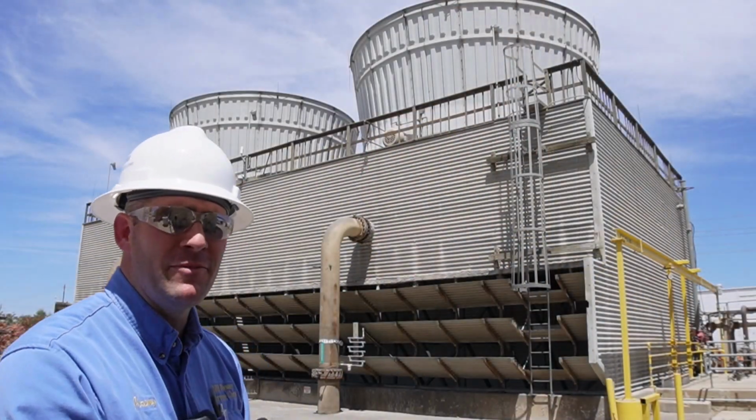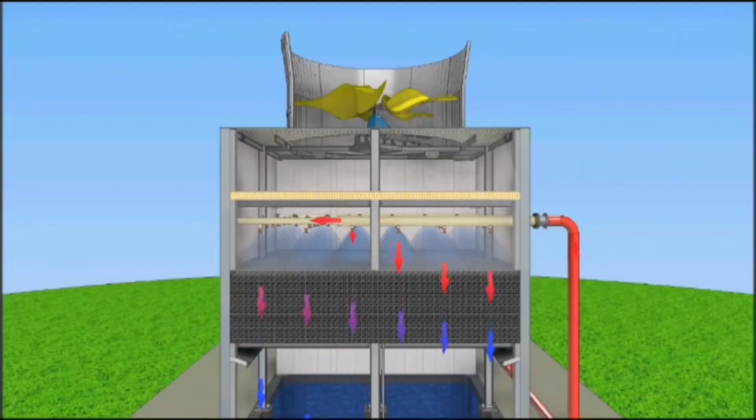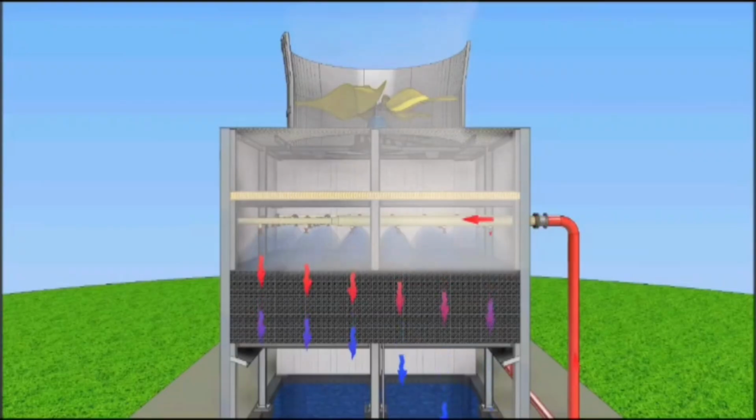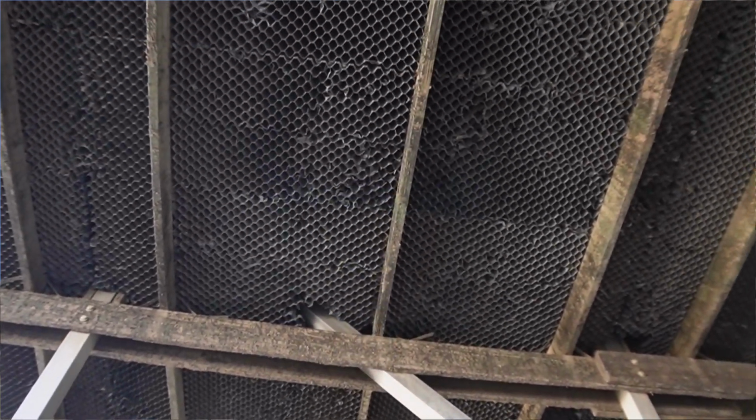If you look behind me, you'll see two large inlet pipes. These are the return flows from the equipment out in the field. When water flows towards the top of each tower, it will then come down and fall through what we call the honeycomb. This maximizes surface area so that the updraft can pull as much heat from the water as possible.